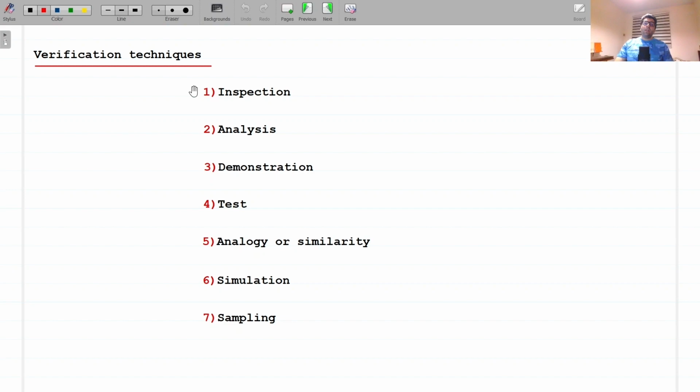Inspection. This technique is based on visual or dimensional examination of an element. The verification relies on the human senses or uses simple methods of measurement and handling. Inspection is generally non-destructive and typically includes the use of sight, hearing, smell, touch, and taste, simple physical manipulation, mechanical and electrical gauging, and measurement.